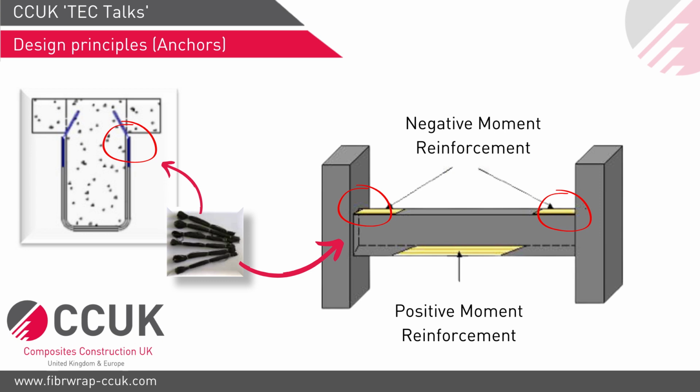So basically what you're saying is if you're wrapping the beam and you don't go to the ends and use anchors, it's not worth doing. Yeah, unless you have the peak stress somewhere in the span, it will not work on that location, because you don't have any anchorage length beyond that point. The other thing is in terms of shear strengthening of the beams.